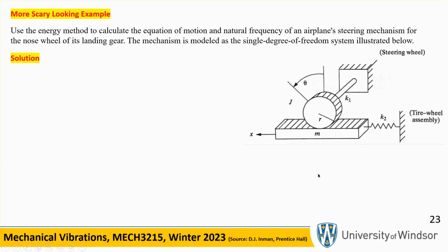If you... yeah, you've got to be careful, because if this thing moves to the left, actually this gear does a clockwise rotation. Yeah, this moves to the left, this does a clockwise rotation. So there may be a minus sign missing from the expression.